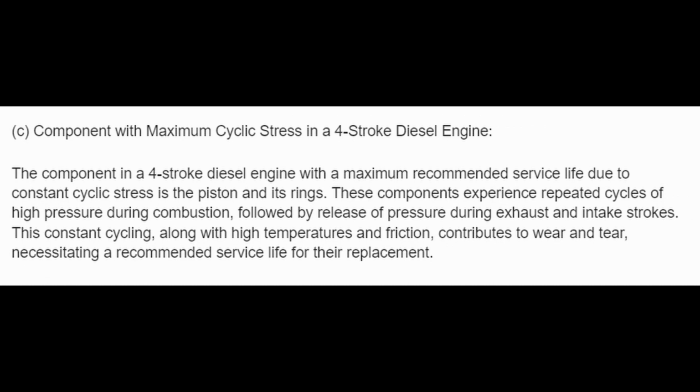C. The component with the maximum cyclic stress in a 4-stroke diesel engine. The component in a 4-stroke diesel engine with a maximum recommended service life due to constant cyclic stress is the piston and its rings. These components experience repeated cycles of high pressure during combustion, followed by release of pressure during exhaust and intake strokes. This constant cycling, along with high temperatures and friction, contributes to wear and tear, necessitating a recommended service life for their replacement.